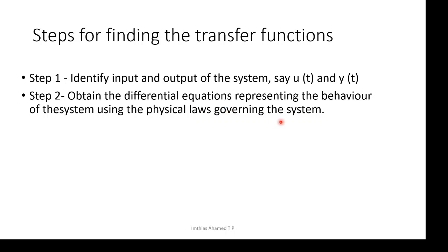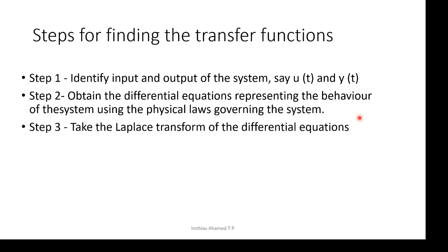Obtain the differential equation representing the behavior of the system using physical laws governing the system. If you are studying a mechanical system, you should know Newton's law. If you are studying an electrical system, you should know KVL, KCL, etc. So, you can write equations. These equations are differential equations. Step 3 is easy. Take Laplace transform of the differential equations. Only minor knowledge of Laplace transform is required.